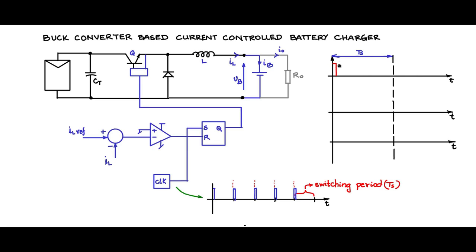At the start of the cycle, you have a small duty cycle pulse, and that is this clock pulse, and it happens at every starting of the period. Now the moment this clock pulse is given, it sets this SR latch. Q is high. The moment Q is high, there is base drive for the BJT or gate drive for the MOSFET, and this is on, and VT gets connected and the inductor is charging up. The inductor current is growing.